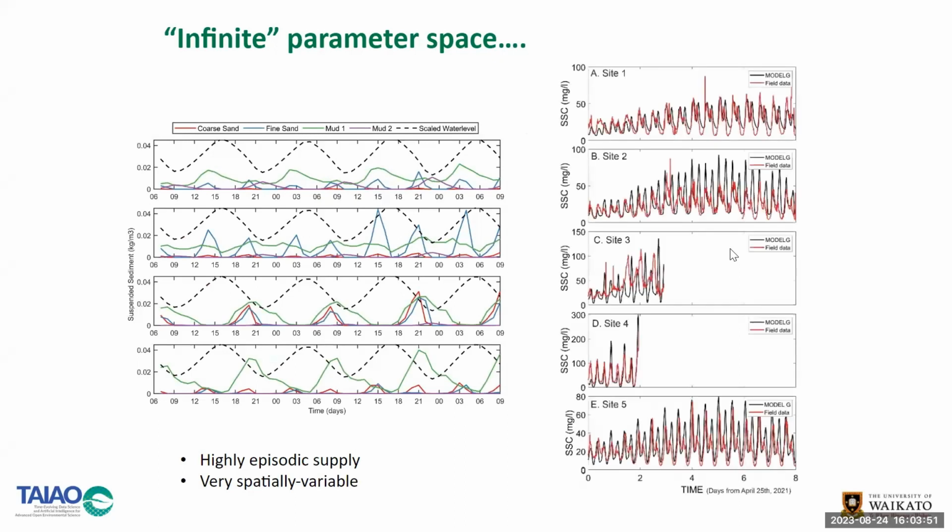Okay, so the problem is this shows you the suspended sediment calibration. And we spent probably 3 months rerunning the model. Each model run takes about 2.5 days, right? And we tried all the different parameters. We don't have very long data sets, only about a month. And the suspended sediments are extremely episodic. If you have a wind event, it picks up sediments into the estuary. And so it's very dependent on the time of the year.